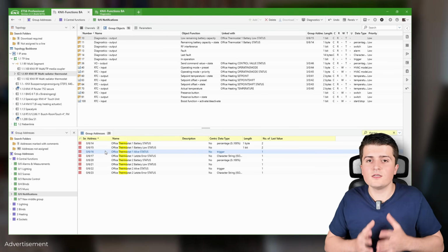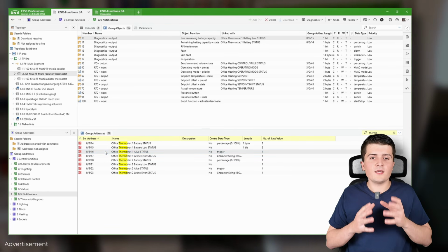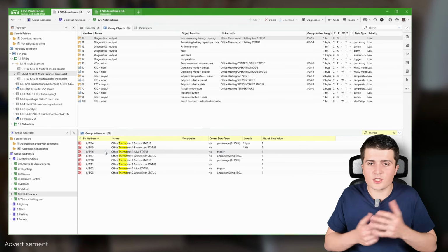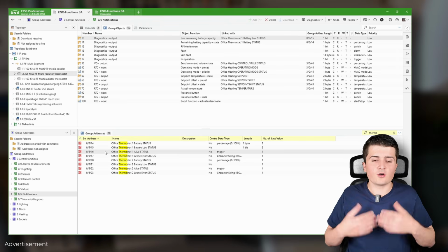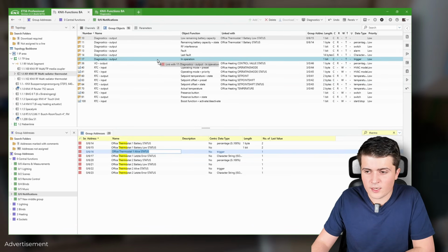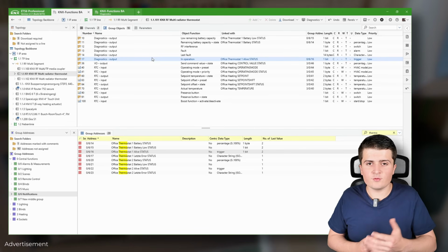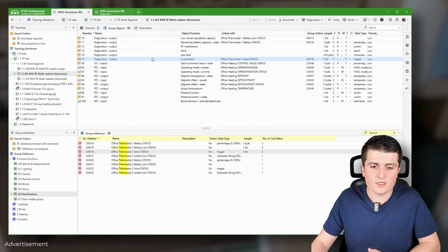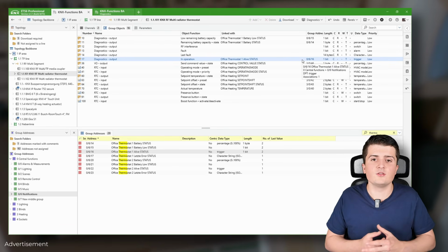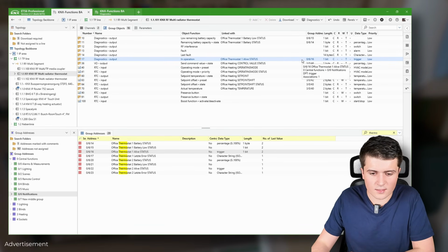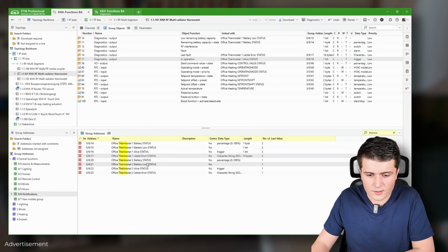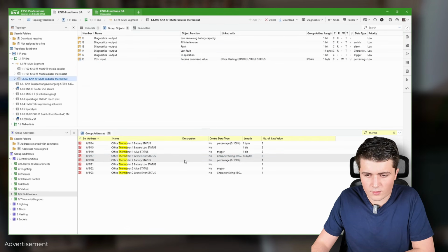and this is something which I would definitely consider to turn on, because with that you can parameterize a functionality with an additional logic editor with which you can control if the devices are still alive. And this is here the in operation mode. This is a bit that is triggered every 24 hours. So every 24 hours, this device will send a true to this group address. And with that, you can monitor if the device is still alive. Then we have the last fault information and the same for the second thermostat.